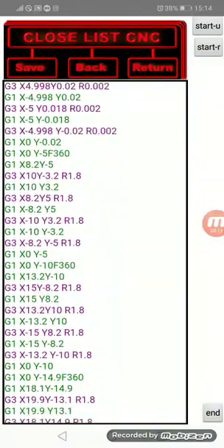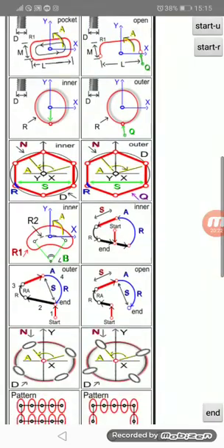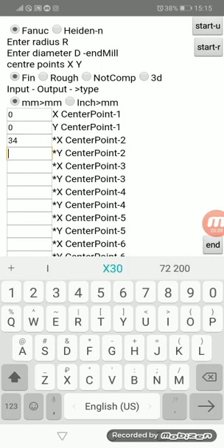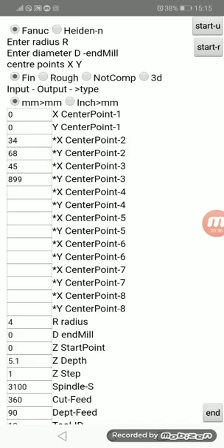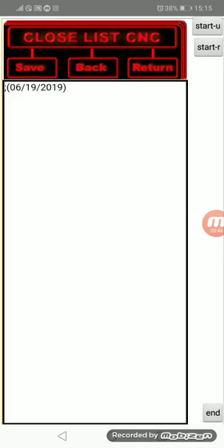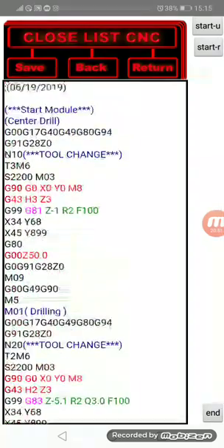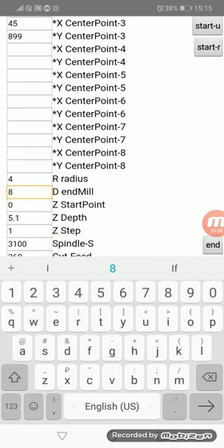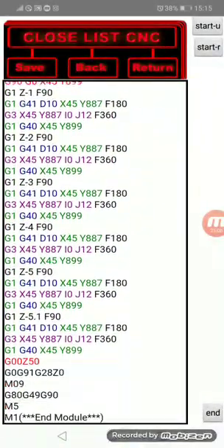It's very convenient. Rough milling, finish milling. Moving on, the holes. You need to set the center point. Let's have a look at the list. The first function is finish milling, second one is rough milling, with the following finish milling. We shouldn't forget to set a diameter. For a rough milling, and then a finish milling.